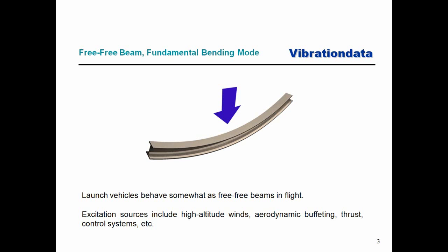So what we have to do as the structural dynamics or the vibration environments engineers, we have to predict ahead of time what the launch vehicle natural frequencies will be, and we need to convey that to the guidance and control engineers so that they can design their control systems with the correct stability for the various gain and phase margins, or whatever they do with that data.